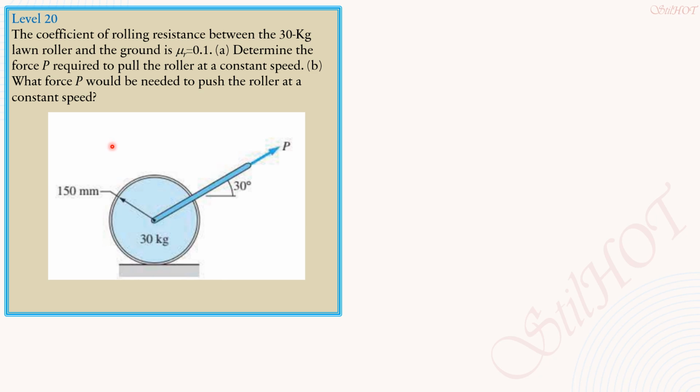So the principle is we just locate point B, where the reaction on the ground and the rim, or outer surface, of the wheel meet or coincide. Then from there we sum up moments about that point so that we don't need to memorize formulas.